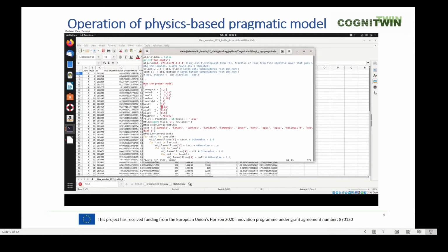And we have emissivities of the outer wall of the ladle, and also internal between the slag and the refractory, and the lid inside the ladle. So these are our parameters, but we also have a number of other parameters that we can vary to do the tuning.